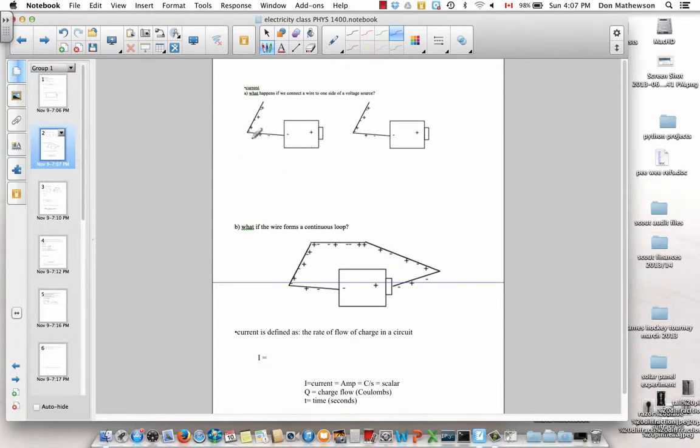Now, if we come along and connect a wire to a voltage source, then these excess minus charges are prevented from going this way by the chemical reactions, but they can go out into the wire, and that's in fact what they do. Because of the electrostatic repulsion, they're pushed out in the wire, and then that sort of causes a chain reaction where minuses get pushed all along the wire away from the minus terminal of the battery, of the cell.